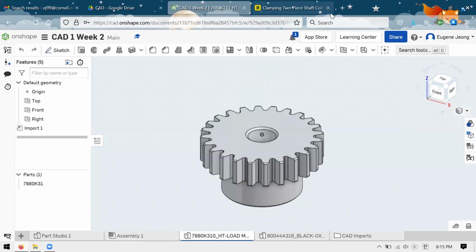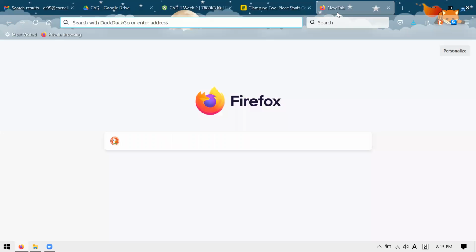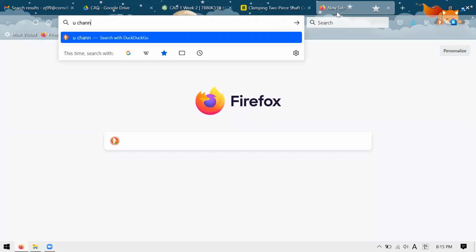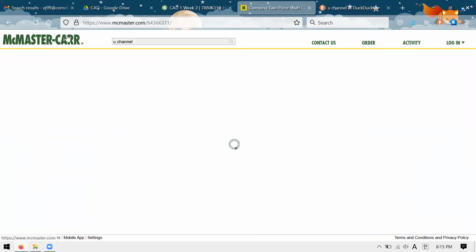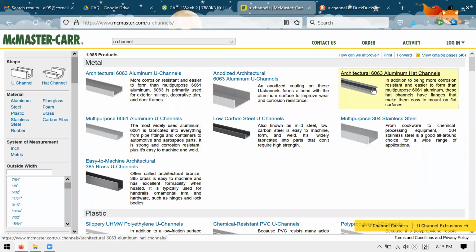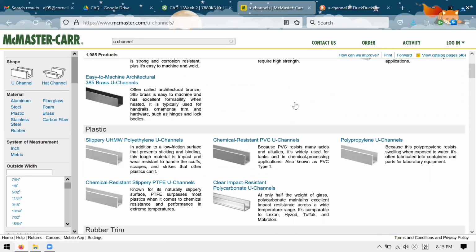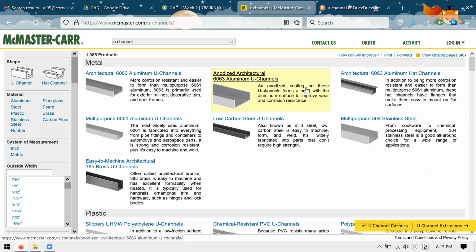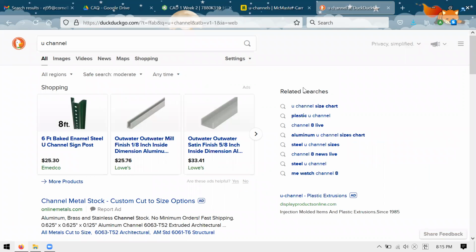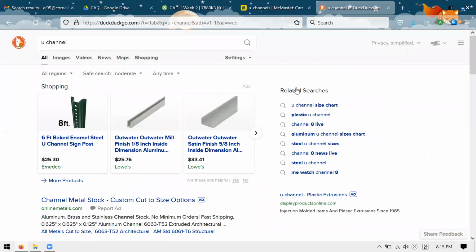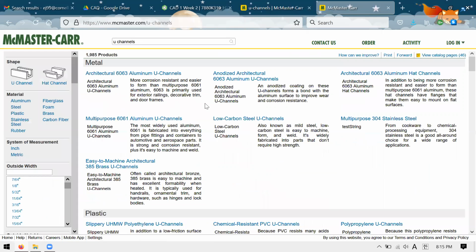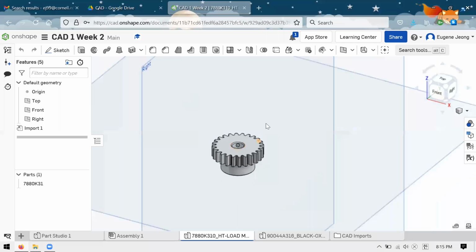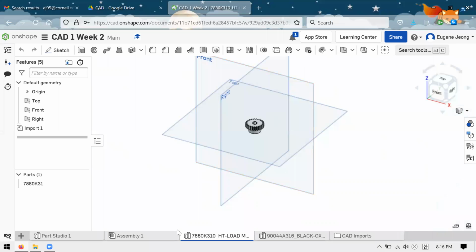So I know someone showed me earlier, they were trying to CAD a U channel. And I told them that there was an easier way to do it. The easier way would be to find the exact U channel that you're working with, which almost certainly is out there. If there is a CAD model, just download that exact part, because that is what you're working with. There's no reason to try to guess the dimensions when you have the model by the manufacturer, exactly nominal to specification. So if you can find it, use it. It'll make your model more accurate. It'll save you time. It's just good.